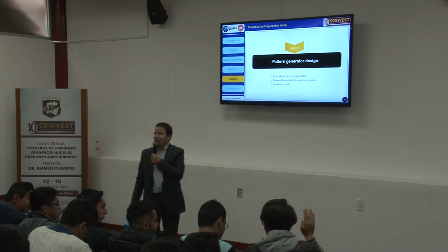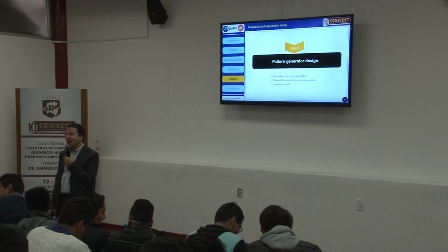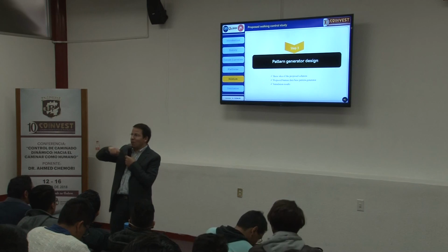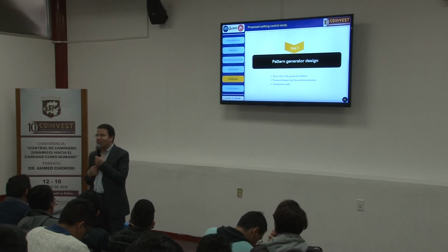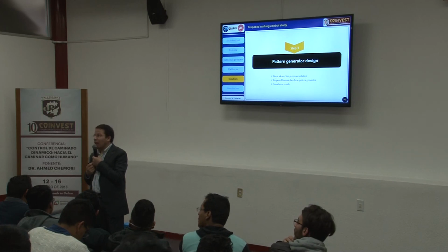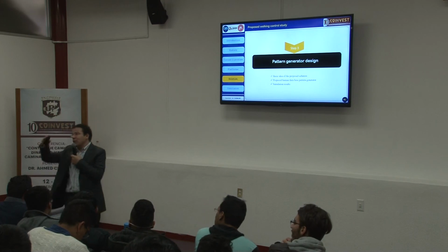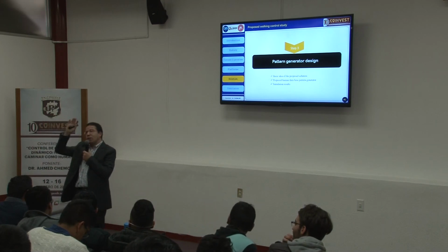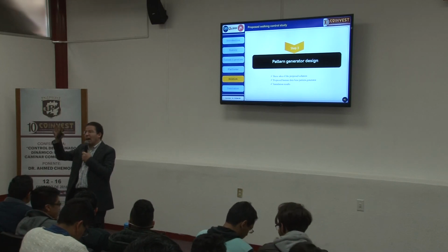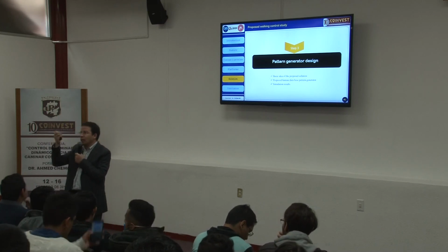Any other questions or remarks? Yes, please. Why use motors and not other actuators? Give me another example of actuators. If we don't use motors, what can we use? Pneumatic. Yes, there is hydraulic. These are other kinds of motors. For instance, hydraulic. If you have problems of high forces or high torques, you can use hydraulic. Hydraulic can provide very high forces.